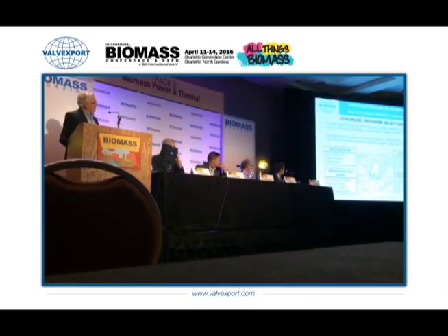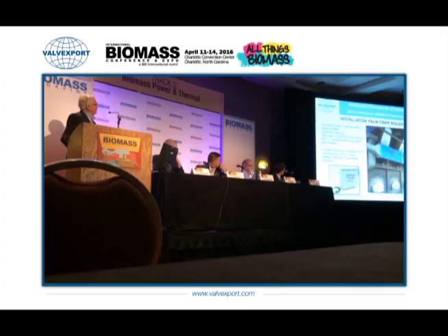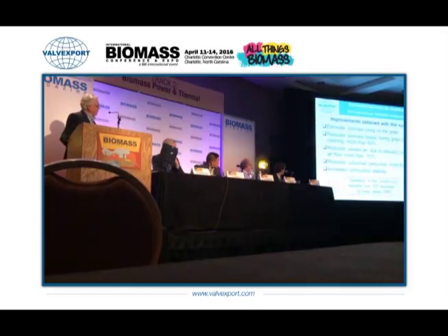We have developed control boards, small boxes, where an operator can select various programs depending on what he sees. So by just turning the selector, he can change completely the program that he's using to locate his biomass. Installation, this is a typical installation in a gas boiler, a 350,000 pound per hour. That's a palm fiber boiler. This is the type of control box that we were talking about.